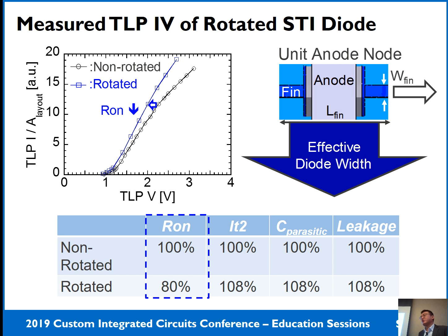Because the charged device model, as I mentioned, is the real primary ESD event in the IC industry nowadays. In fact, they are discussing reducing the CDM requirement, but not only because of the technology issue, but also because your package becomes bigger and bigger. This charged device model is strongly impacted by the parasitic capacitance from your package.